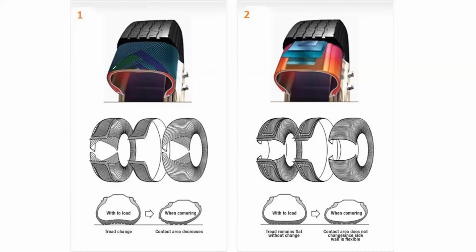Even though a tire seems to be just a rubber tire, it's not exactly like that. It actually has a steel or fabric interior, fabric ribs inside. These ribs support the weight and work against deflection. As shown here, when the vehicle is taking a turn, the weight of the vehicle is trying to move in the opposite direction of the turn.